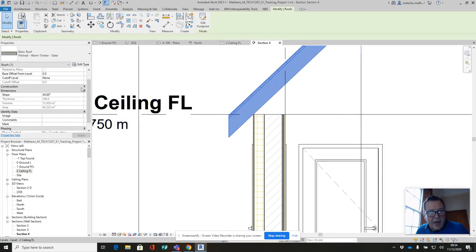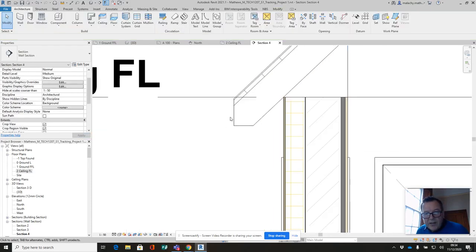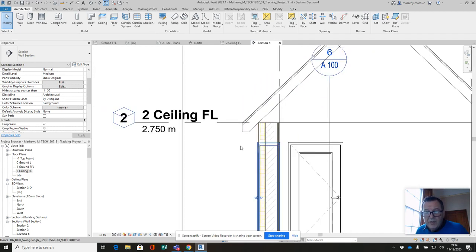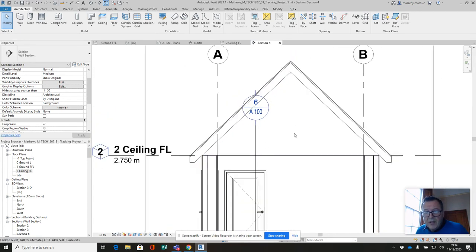So the default construction here is plumb cut. And we're going to pick a two-cut plumb, which gives us access to the fascia depth. And we're going to put in a 175 fascia. Apply. Now you can see that it has cut the fascia down. We've got this little return here, which is very handy because it allows us somewhere to fix our soffit onto the wood as well. So that's our first little change that we're going to do there. Apart from that, that's pretty good.